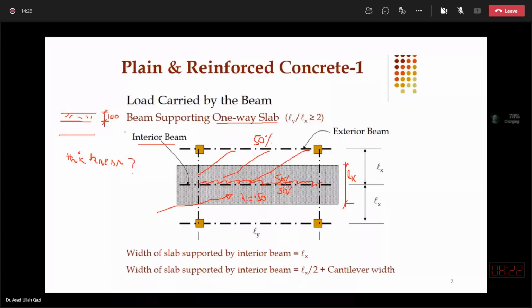So it depends on the selection of the finishing materials which are superimposed on the slab. So if from the architecture working drawings we have the idea of the floor finish, and the thickness decided by the structural engineer is known to us, then I will convert them into pressure by multiplying the thickness with the corresponding densities.